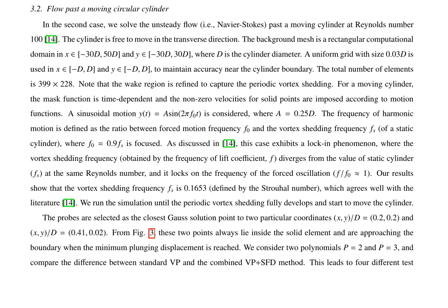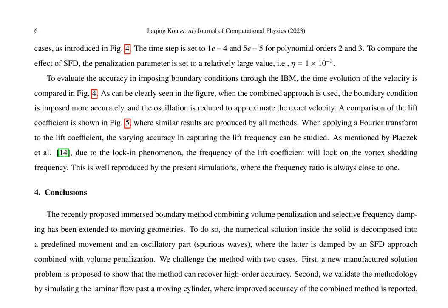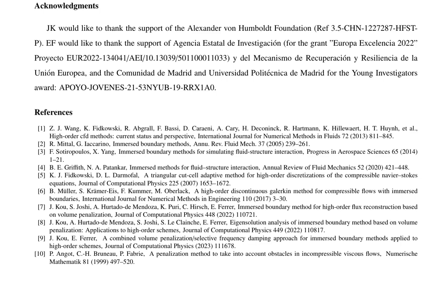around moving boundaries. The immersed boundary method is extended by combining volume penalization and selective frequency damping for moving geometries. The numerical solution inside the solid is decomposed into a predefined movement and an oscillatory part, where the latter is damped by the SFD approach. This method is tested with two cases: a manufactured solution problem to demonstrate high-order accuracy and the simulation of laminar flow past a moving cylinder for validation. The combined method shows improved accuracy in both cases.